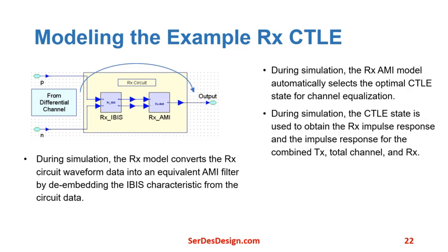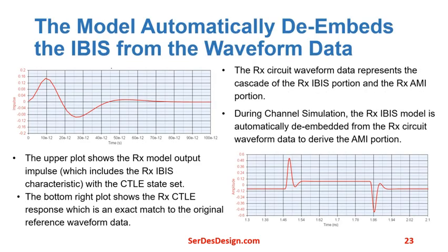The CTLE configuration is used to obtain the Rx impulse response and the impulse response for the combined TX, total channel, and Rx. The model automatically de-embeds the IBIS from the waveform data.